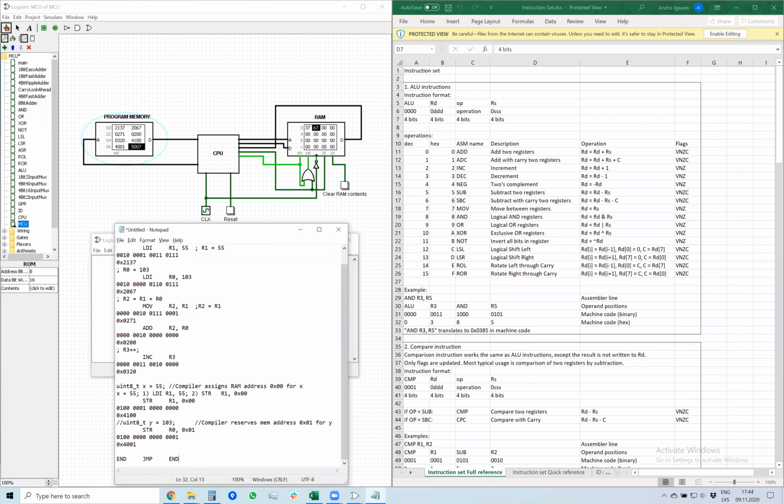And this is the first place where we are using labels. So a label is basically the location in flash memory of this instruction. Or since each instruction is one word inside the program memory, it's also the line number, counting from 0.